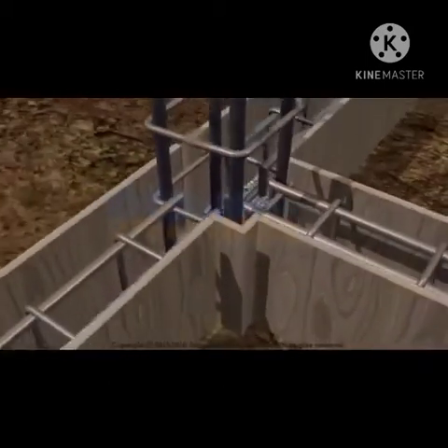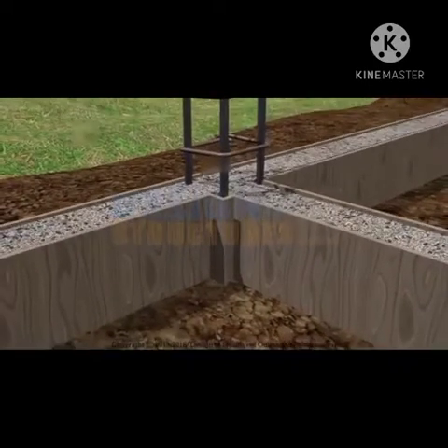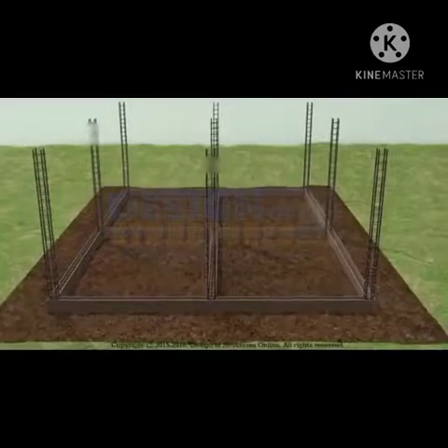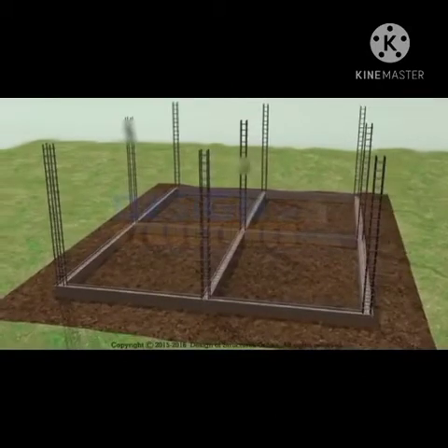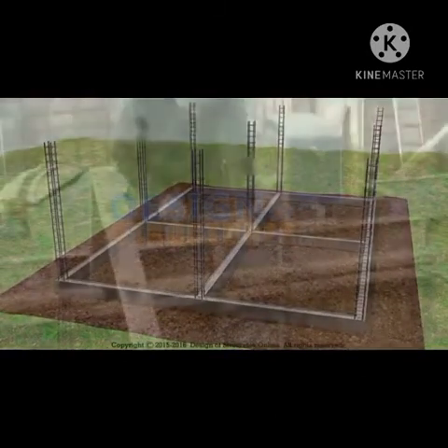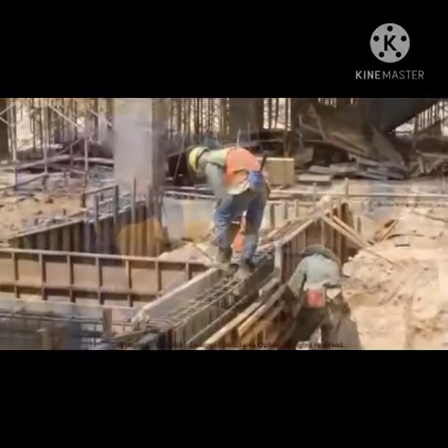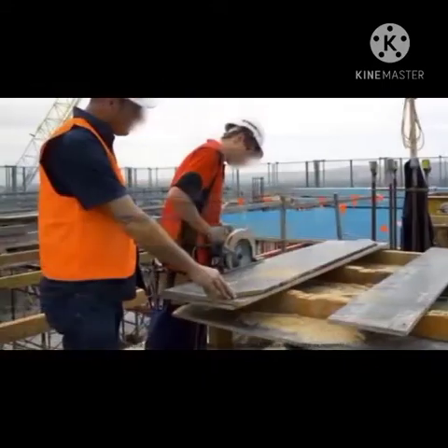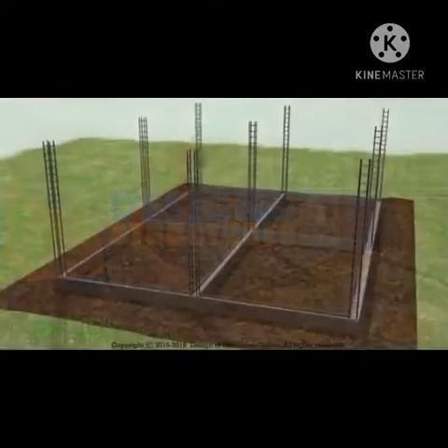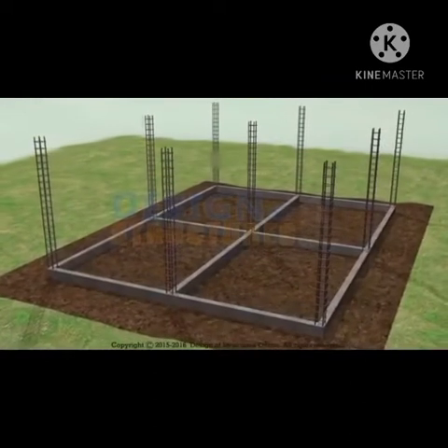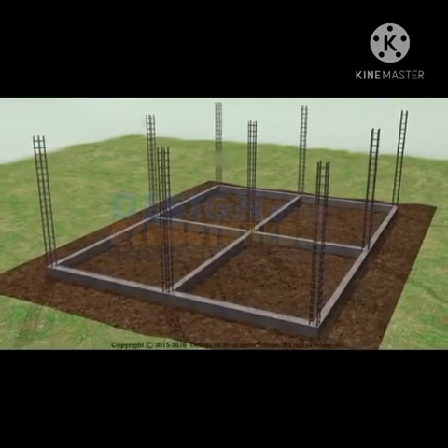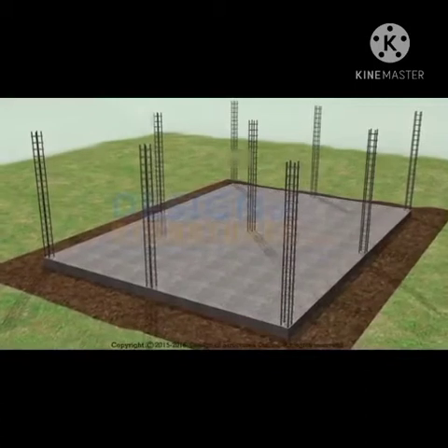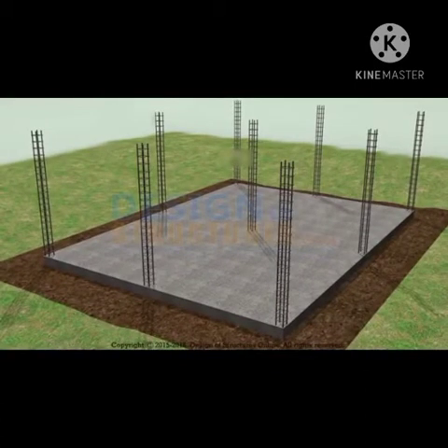Beam concreting. Beam is poured with concrete with grade mentioned in the drawings. The positioning of reinforcement should be properly aligned. Shuttering parts and connections should be arranged in a way that makes formwork removal easy and simple, prevents damage to concrete and formwork panels so that it can be reused without extensive repair. Slab concreting. Grade slab requires no reinforcement as it's resting on ground strata itself. Top of plinth beams and grade slab should be at the same level.